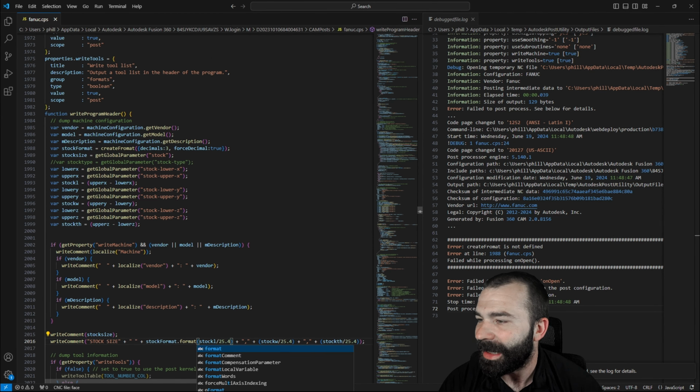So as you can see, it has now limited our decimal to 3 decimal places based on that formatting that we've plugged in. So again, we can do the same thing with the other two. So again, we have our X, our Y, and our Z. I'm just going to do a copy paste. I'm going to go ahead and hit save. And now you can see that we went ahead and did a cut, not a paste. So let's put that back in the first one also. You can now see all 3 sets of our numbers are limited to 3 decimals inside of Fusion 360's post.